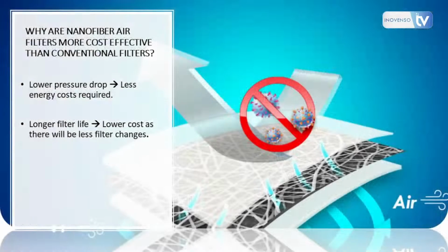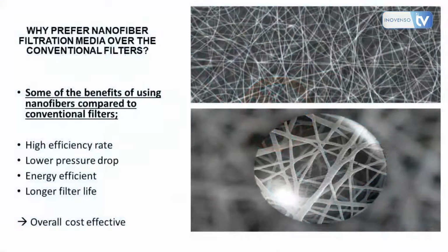Right. So before I go into that, can you go back to the previous slide, please? Thank you. So I'd like to say these masks and these air filters, they have several sorts of standards and tests that clarify them or determine them to have a particular ranking. What happens is there's an EN rating for Europe, there's an ISO rating for the international scale, and then there's the American rating, which is ASHRAE 52.2. Each of these have their own specific testing. Mostly, they align a lot. They're very similar in many ways, mainly with two parameters, which is the filtration efficiency and the pressure drop.